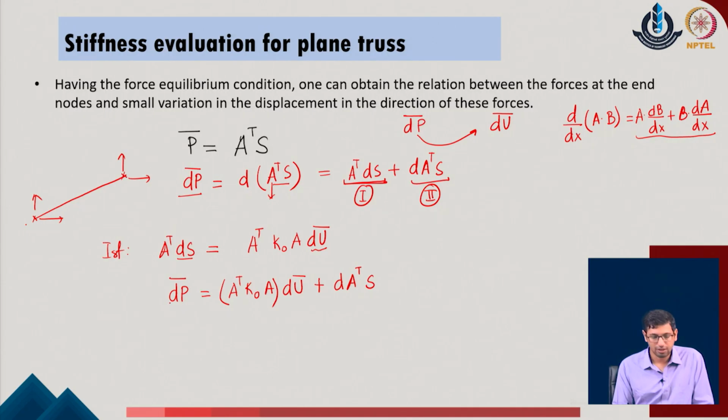So, what we realize is that if this is the load increment and this is the displacement increment in the given problem, then this is supposed to be the stiffness of the given system. We identify that this is the stiffness which we describe again in the local coordinates of the given system, and this is the stiffness which is identified with respect to the terms which are included in the A vector of the given system.